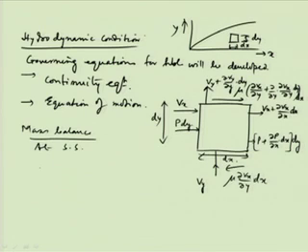So, from there, if we write the mass balance at steady state, that is equal to rho Vx into dy, that is entering from this side, plus rho Vy into dx, that is entering from the bottom side. What is this? This is the mass, because Vx is the velocity, dy is the area. So, this is what is to be said.